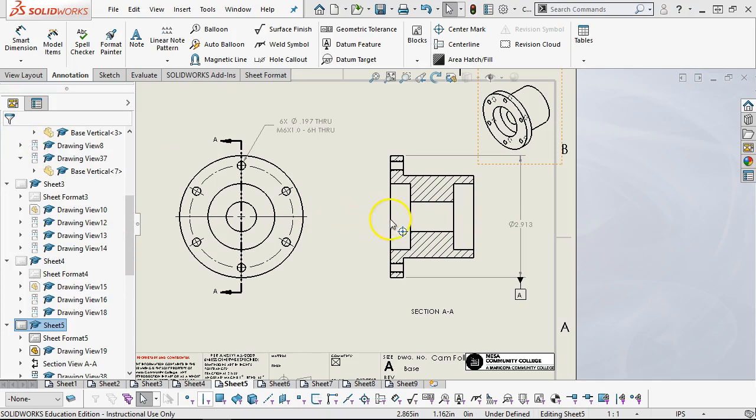All right, we can center the keyway as a position. And since we're going to keep updating these, let's go with the A datum. We have the basic dimension, and then the geometric tolerance we'll pick up is the surface of profile. And let's give it 5 thousandths in relation to A. We'll place it.